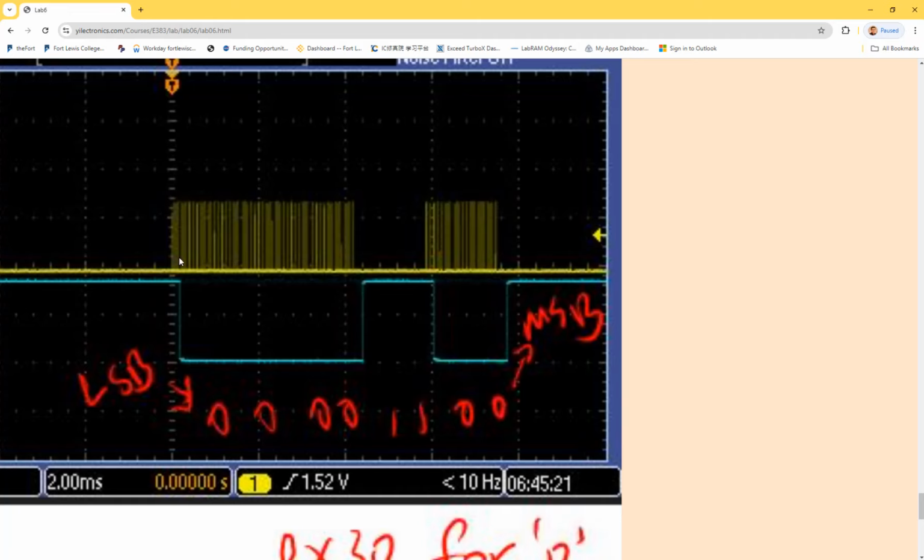PWM pulses are sent to the BJT transistor. The BJT transistor converts them to light pulses. Light pulses are sent into the air, the photons are received by the decoder, and the decoder decodes it, boom, puts it here. So here's the time delay. The time delay shows the whole description I just made.